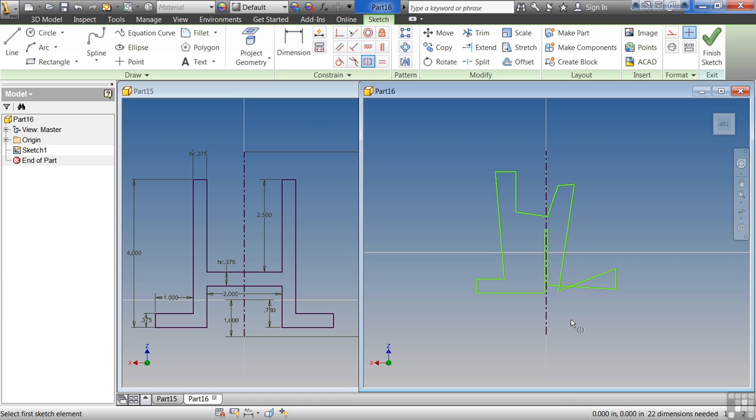Once you start adding symmetrical constraints, if Inventor goes wacky on you and gives you a Jackson Pollock looking design, the best thing to do in an initial sketch like this is to undo. We can go to the next symmetrical constraint. Say this outer line here, inner lines. See the feet? I can start giving it some of this intelligence.